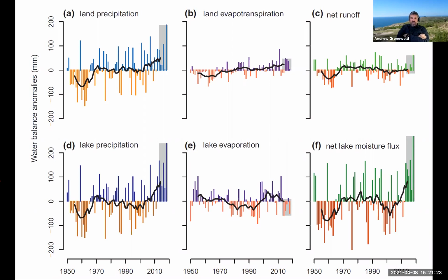But it's important to note that on a very, very local scale, we could use eddy covariance meters or other flux measurement techniques to understand ET on a very local scale. The broad scale data sets that we're looking at on this image in the top panel B, and for other basin scale estimates, are in general, and in this study, using a combination of models and model simulations that have, at specific points across the landscape, been either calibrated or validated to in situ monitoring infrastructure when and where it's available.